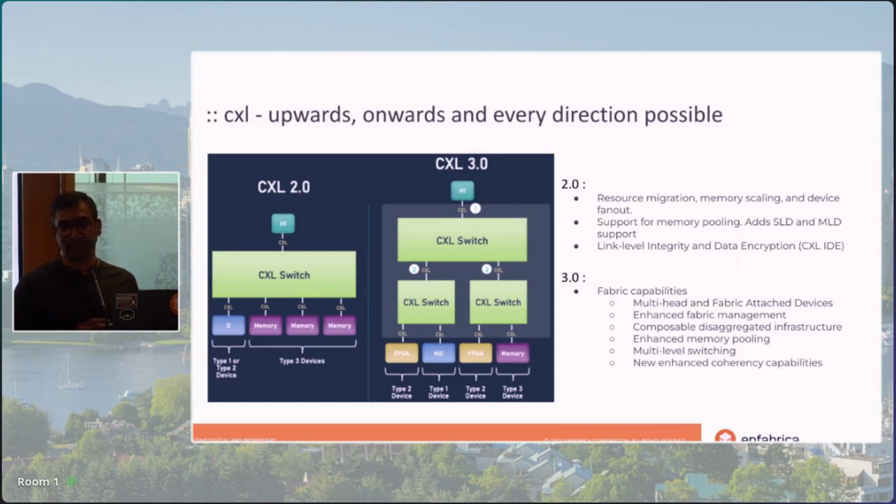And why is that so? CXL 2.0 adds the notion of being able to create memory pools and wide switched layers, as shown in the picture on the left-hand side. This allows us to plug in type 1 or 2 devices as individuals, but more importantly, a group of type 3s that can be presented to a group of hosts across some limited boundaries.